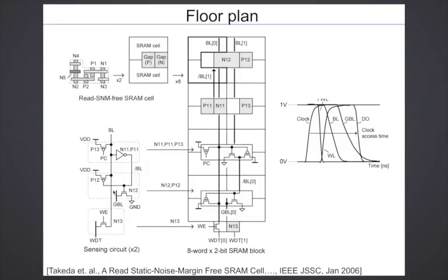Whereas in a memory cell, if I have a single column of 64 or 128, which is what is done in super threshold, you have an on device, which is an access device, which is also in sub-threshold, and you have all the off transistors, which are also in sub-threshold. So you can end up with failure. The on cell will not be able to overcome the leakage of all the other off cells. And that is the reason why you have to go to more extreme partitioning as you go down in supply voltages. It's the same argument we made for muxing.